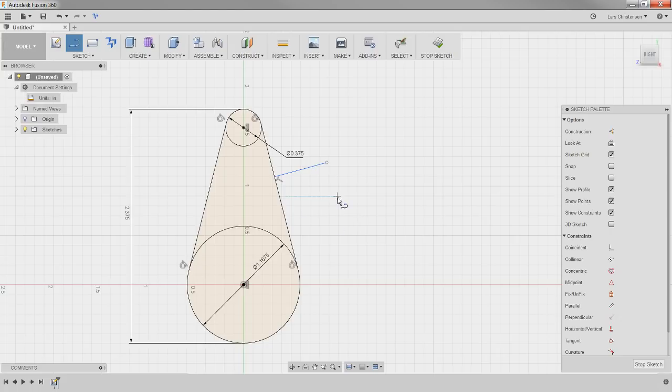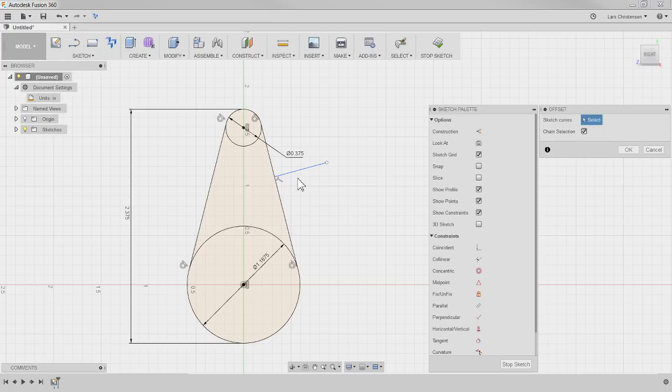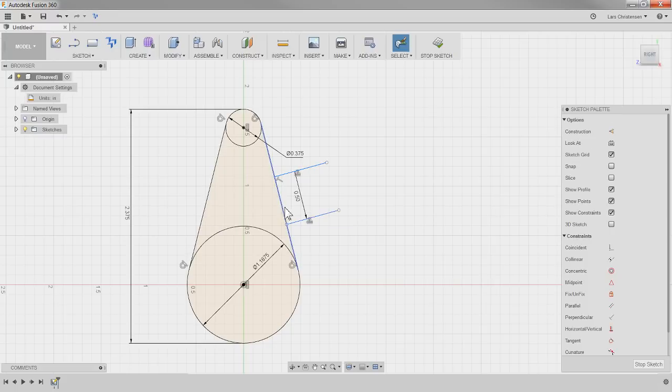Another trick here could be the O for offset. Select this, and then we could make an offset line out, making that 1/2 inch. So this is kind of our opening. Now, I don't really need these lines for drawing. They're more reference or construction. So we could click on these 2 lines, hold down Control to multi-select, and click over here to make them constructions. So now they're not really mattering much. Is this useful? I hope you're picking something up.